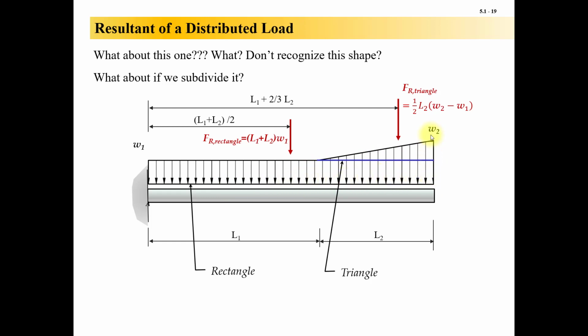You've got to subdivide this up into the right shapes underneath it, that together, when you piece them back together, they make an exact match of the original loading. Otherwise, you're going to double up load, and that's no good.